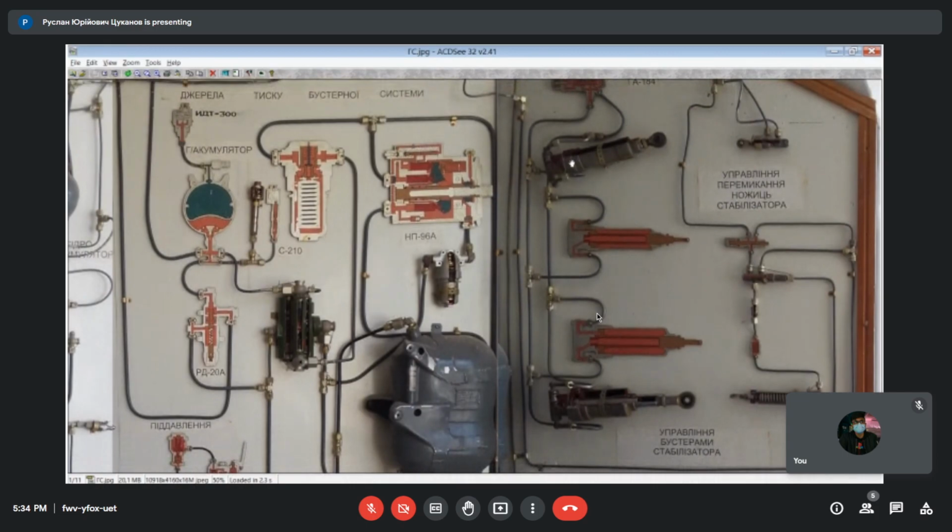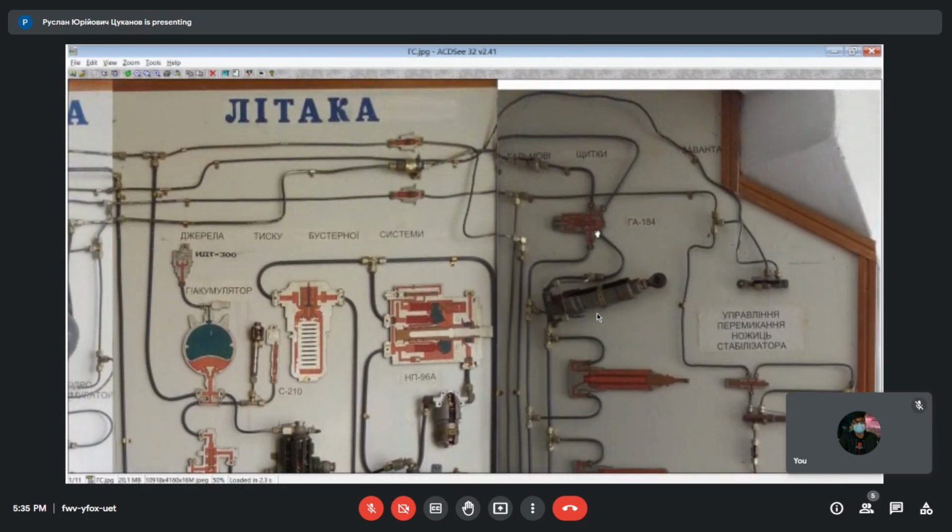Here you see four actuators, two in the top are of low size, two in the bottom are of big size. These are also feedback devices, which allow deflecting the speed brakes or air brakes outwards and decelerating the airplane in flight when you need to drop the flight speed. For maneuverable airplanes, it's a very important device.